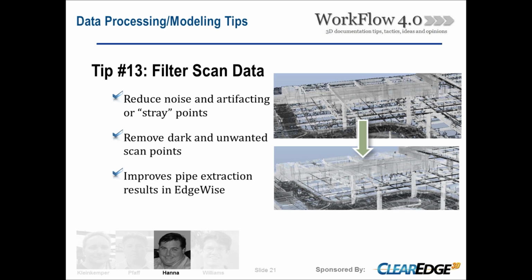We run filter routines to reduce stray points and artifacting on the pipes, removing dark points or unwanted scan points, and we're yielding much better results when we run the auto extraction pipe tools. So this should be standard in a process, but I can't emphasize how important this is: before you start modeling, clean that scan data up as best you can, running filters.